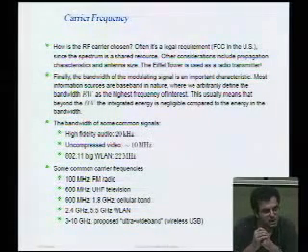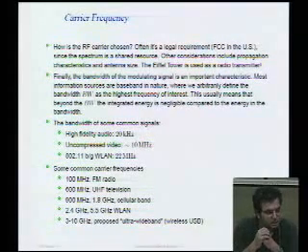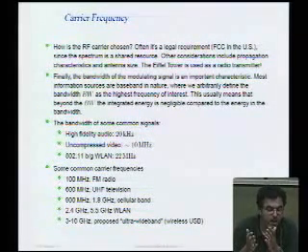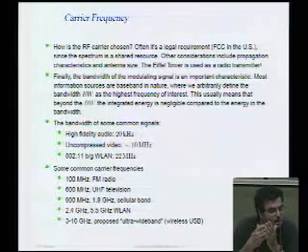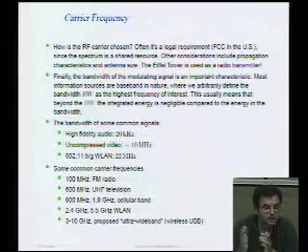That's a very small fraction of the bandwidth. So I could, let's say, allocate frequency from 1 gigahertz to 1.01 gigahertz and have a bunch of channels in there. But if now I want to transmit high-speed data, let's say wireless LAN, then I may need 10 megahertz of bandwidth or 50 megahertz of bandwidth. And so then the number of channels that I can use goes down.